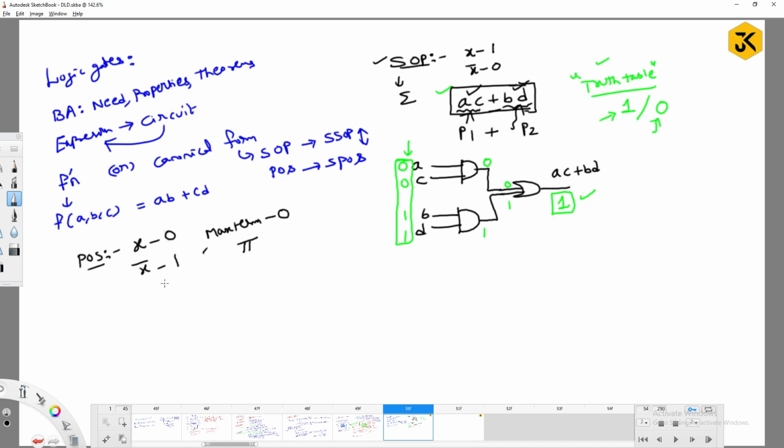So guys, no need to apply all those things. I will try to take another equation that is in the form of (A plus C) and (B plus D), right? So can we express this in the form of a circuit? Yes. First I will complete A plus C. A is input, C is input, and we have an OR gate, right?